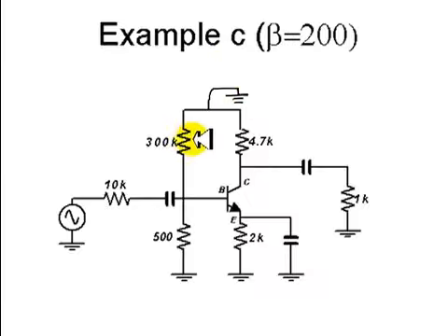So this resistor actually is in parallel with this one down here, and this is also connected to the reference node. But not only that, in AC those three capacitors are like short circuits, like so. Observe then that in AC, this shorted capacitor here is connecting directly the emitter to the reference node.